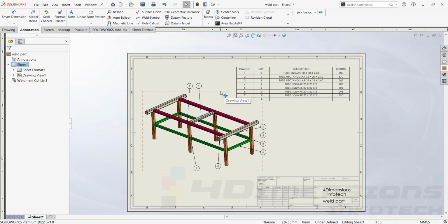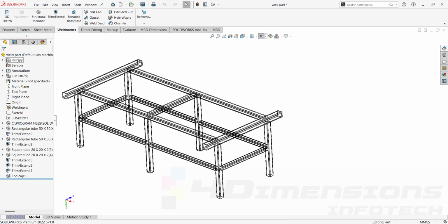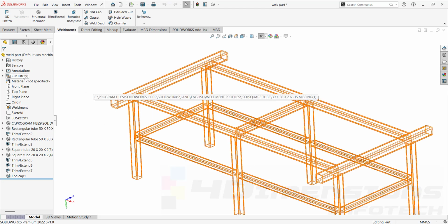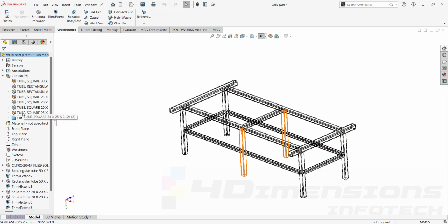So to update those values, I'll open this part or structure here. Now you can see this cut list option showing here. Cut list means nothing but it shows all the individual or single bodies which are utilized to make this full structure. There are 25 items being utilized to make this structure. I'll drop down this arrow, and in this arrow you can see all the standard structures being shown, and here is the last part which is not shown by the properties.